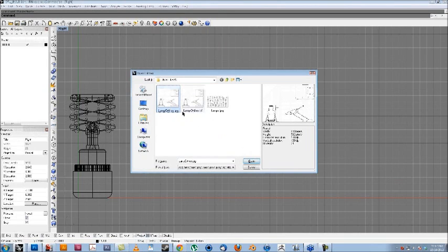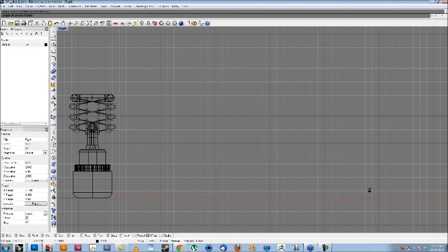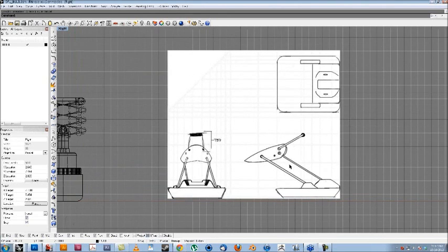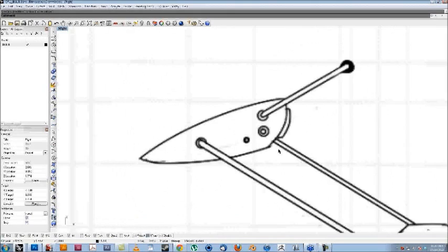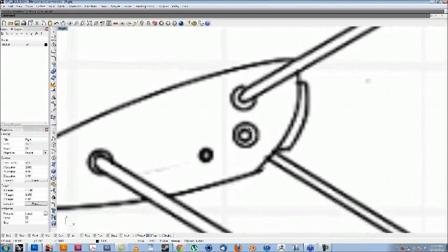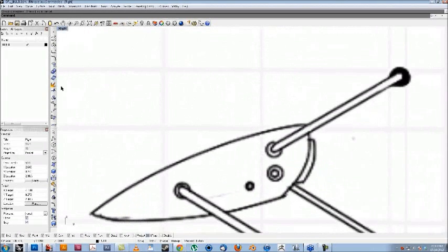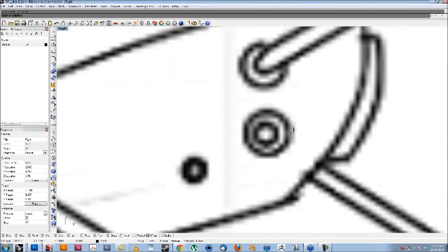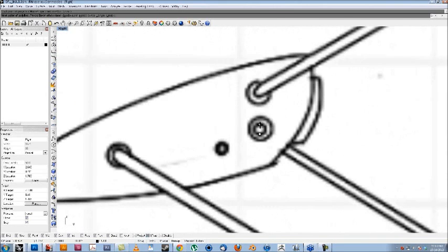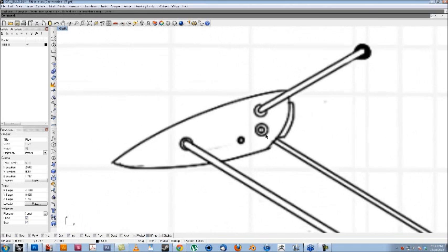and then you can put a whole slew of different file types in there, and then just drag out your size. Now, one quick thing to note, you actually bring up a great point with this, which is how do I know what scale this is? Now, you could use the grid units, but one thing that I always do is I just find a line that I know is going to be, so I know that the tube or the pipe that's going to run down these arms is going to be 0.125.